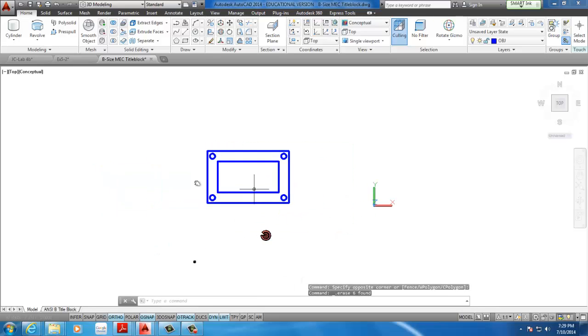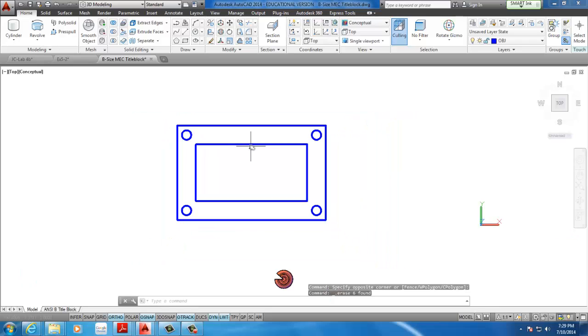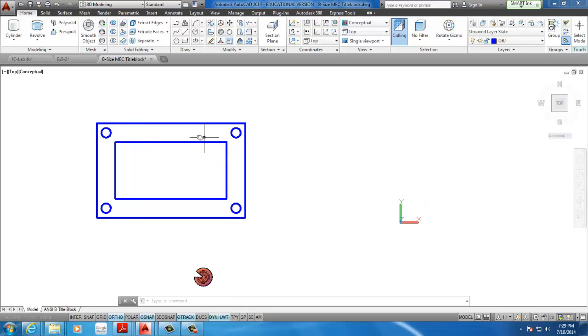Again, so we have this, and then finally we have one more part that we need to do, which is the elliptical cylinder, which is 80 by 40. So to do this one, it's going to be a little bit tricky because I need to create the center of it and actually create the ellipse. The way I enjoy doing ellipses is I create a rectangle first of what I want the ellipse to fill up, and from there I create the ellipse.